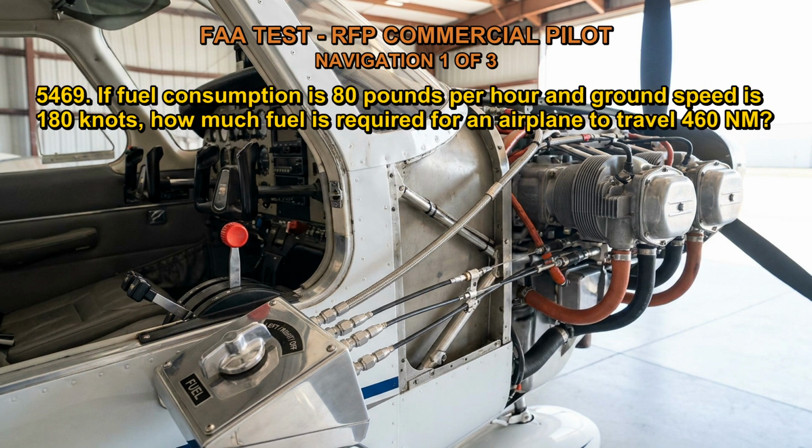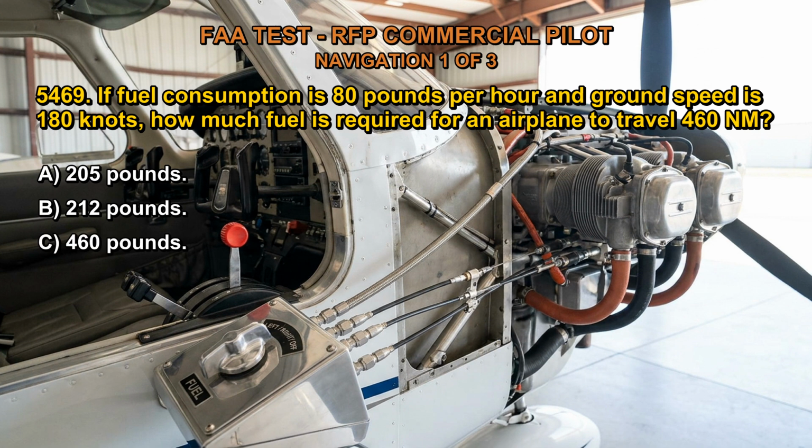5469. If fuel consumption is 80 pounds per hour and ground speed is 180 knots, how much fuel is required for an airplane to travel 460 nm? A. 205 pounds. B. 212 pounds. C. 460 pounds.